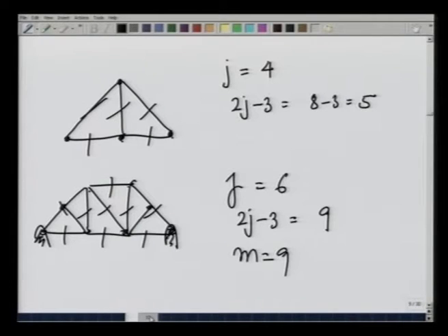You notice that both the ends are put on a fixed point. Actually, this makes the system indeterminate, because the number of external forces is now 4. We could make it determinate by putting the right hand side of the system on a wheel or on a roller. Let us take one example of this, and this is a very particular structure that I am taking.